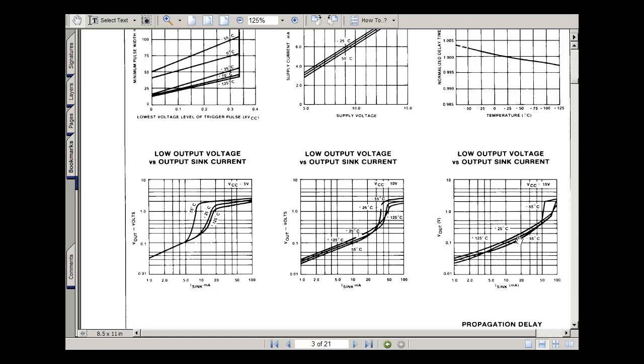And again, this is a plot really of the collector current versus the collector emitter voltage sideways. This kind of goes back to vacuum tubes and how they show data sheets, but anyhow, this is the collector emitter voltage versus the collector current. And again, it looks like it's a straight line on a log scale here. So we're doing log this way and a straight scale this way. Here's where the transistor starts to go active over here.